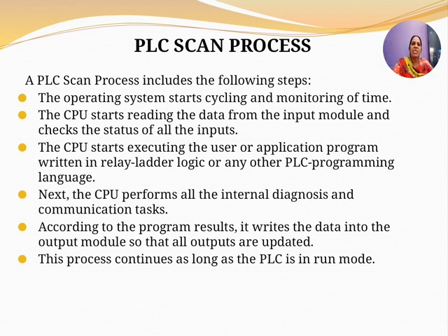So in the PLC scan process, the operating system starts cycling and monitoring of the time. The CPU next, what does it do? The CPU starts reading the data from the input module and checks the status of all the inputs. Then the CPU starts executing the user or application program written in relay or ladder logic or any other PLC programming language.